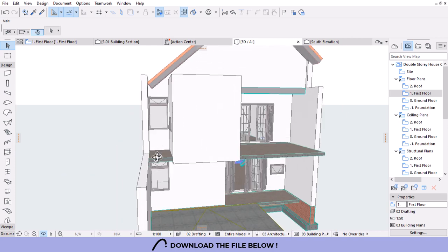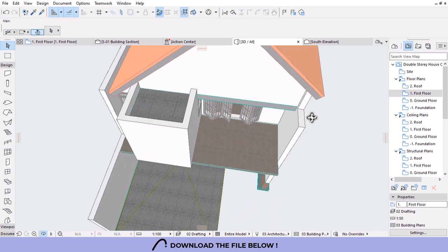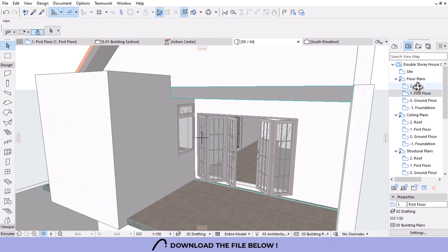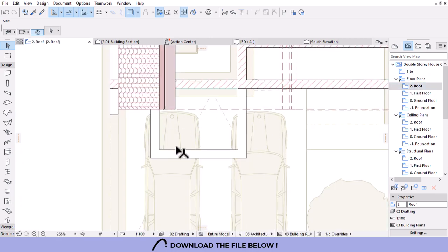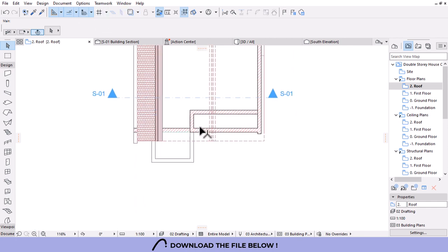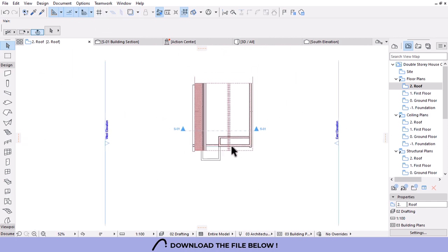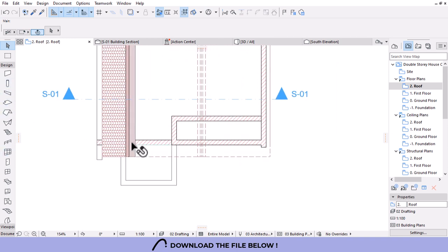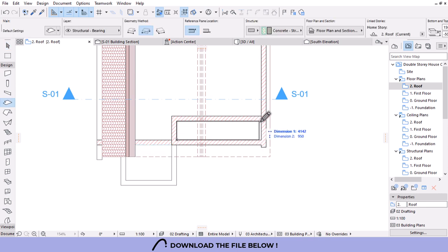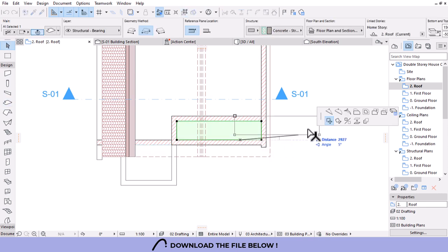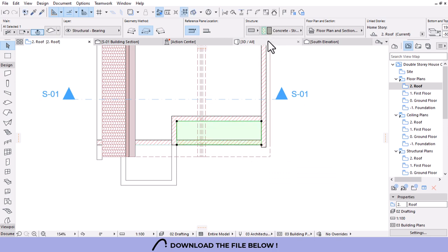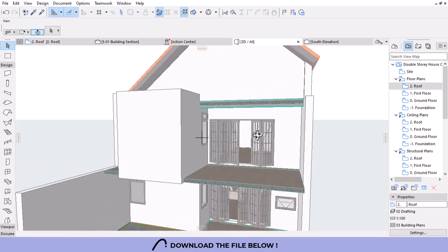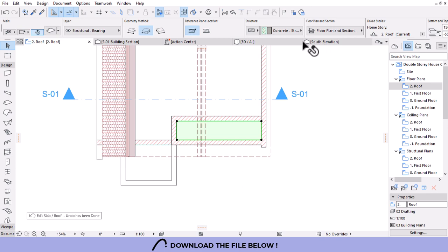Yeah, and then we've created a cap already there, but we need to go to the roof plane and place a slab there. So I would switch off the trace reference, then it's here, pick a slab and then fill this area. Maybe stretch it to there. Let's check on a 3D. Oh, this shouldn't go all the way. Let me leave it there. Perfect.